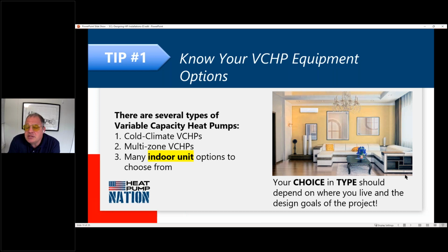All these heat pumps, just so you know, all heat pumps are rated for their capacity at 47 degrees Fahrenheit. When I say that they're able to produce 100% rated capacity at 5 or whatever, I'm saying that the same number that they can produce at 47, they can continue to produce at 5 degrees Fahrenheit, two hugely different numbers. So if a heat pump can do all of these wonderful technological things to continue producing heat at 5 the same level as at 47, this is amazing, right? This is what we've all been waiting for.